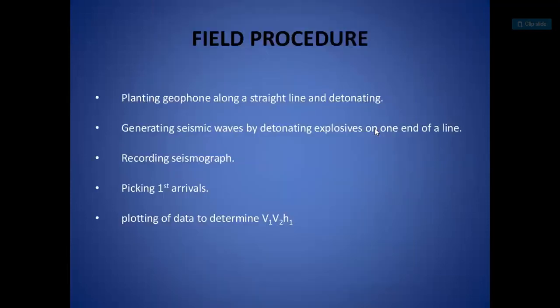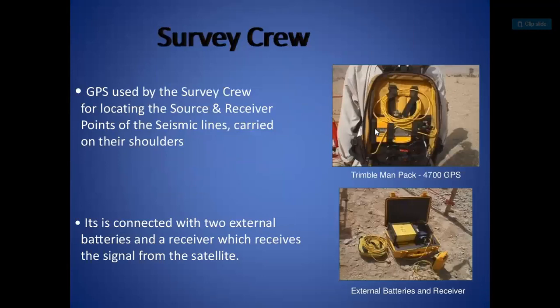And field procedure, guys: planting geophones along a straight line, and generating seismic waves by detonating explosives at one end of a line, recording on the seismograph, picking first arrivals, and plotting the data to determine V1, V2, and H1.